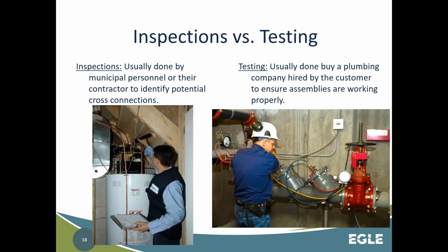So now, testing. Back before rule changes, in order to test devices or assemblies, you needed to be a licensed plumber. Okay, that has changed. There is a certification offered by ASSE. You can become a certified backflow tester, and it's the ASSE 5110 certification. You can find licensed testers on their website. Go to ASSE's website and look up licensed testers for your assemblies.